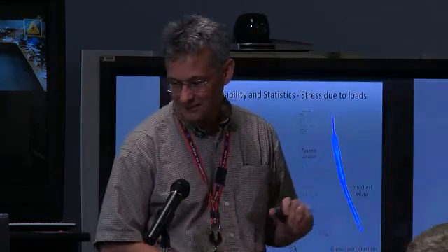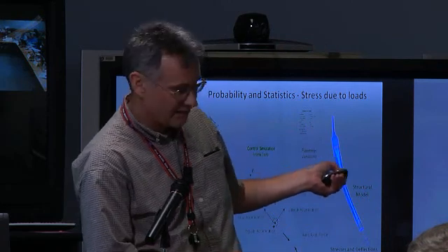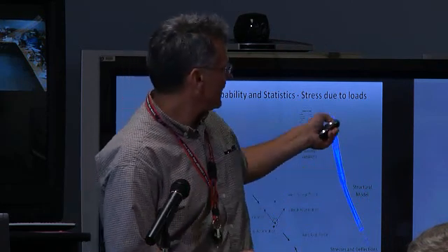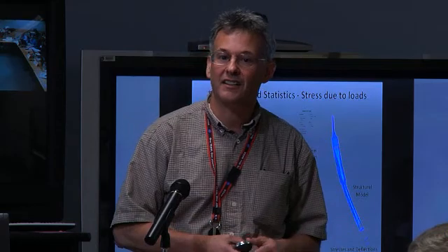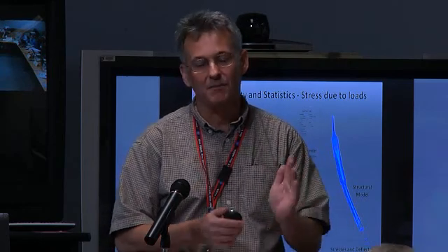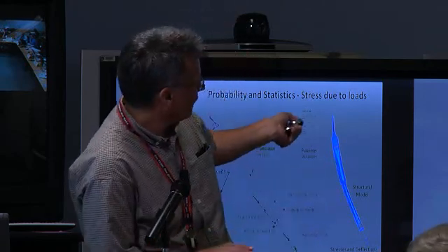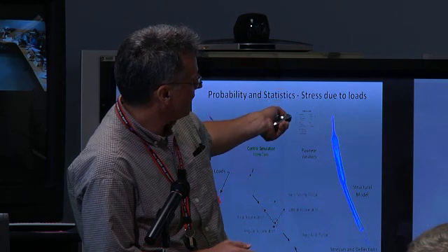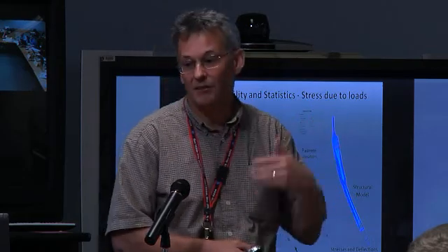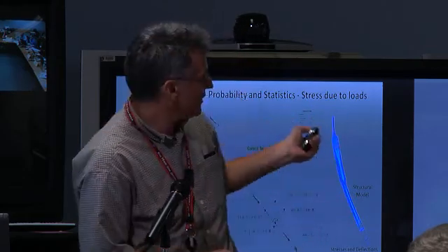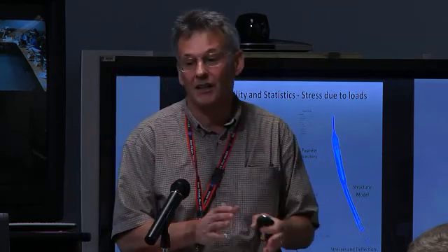All right, so this is showing some of the simulations that were done back when developing this vehicle. What are your parameters? I think Juan talked about Monte Carlo simulations. Monte Carlo simulation essentially is you've got all your analyses that are deterministic, but you have to have a way to vary your input parameters according to the statistics of your inputs. So in this case, we have a lot of data on wind profiles. Each of these little curves, going from top to bottom, is a different wind profile. And we know a certain wind profile happens with a certain frequency. So that's one of the inputs to the Monte Carlo simulation of a whole ascent trajectory.